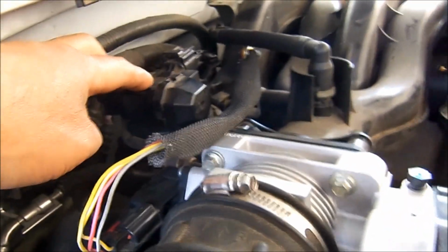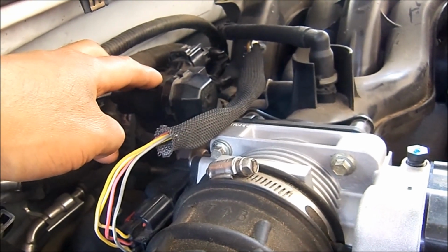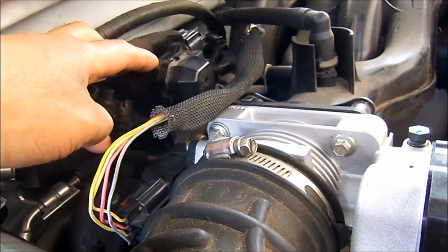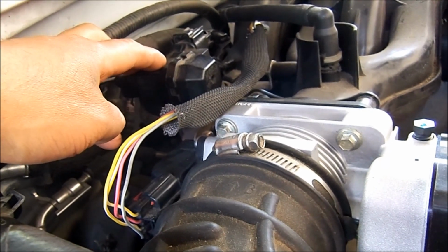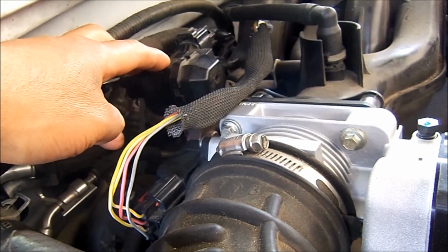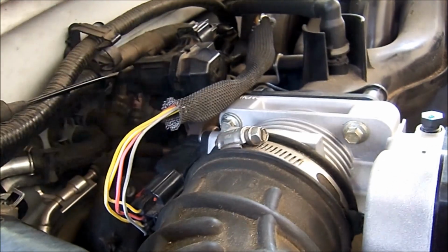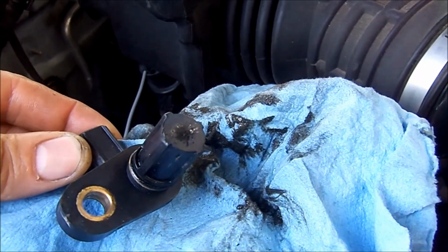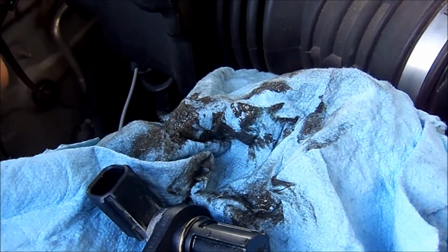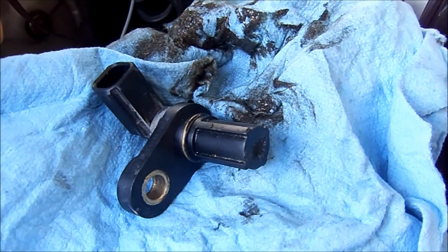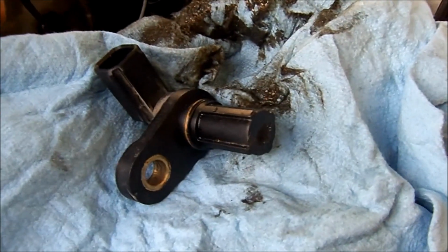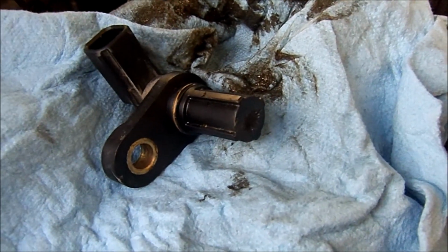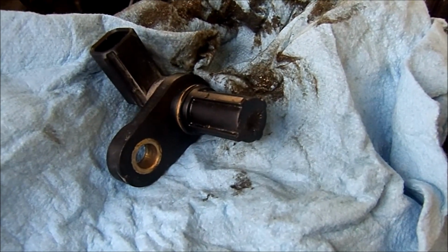So this will cause the throttle actuator to go into forced limited power. Your 3 speed sensors or any gear ratio error on your transmission will cause the same, the throttle actuator going into forced limited power. And of course, like you see here, the rear ABS or the front ABS sensors will cause the throttle actuator to go into forced limited power. Okay, so let's go back to the truck. Let's clear all the codes and reset the keep alive memory.